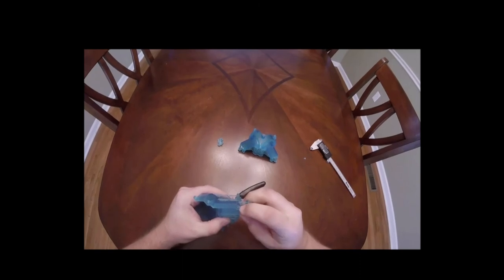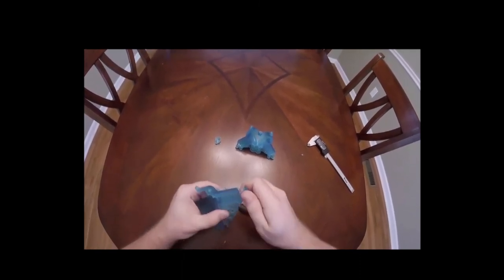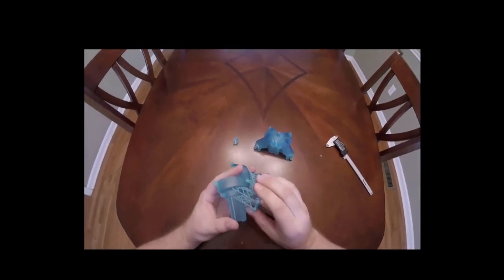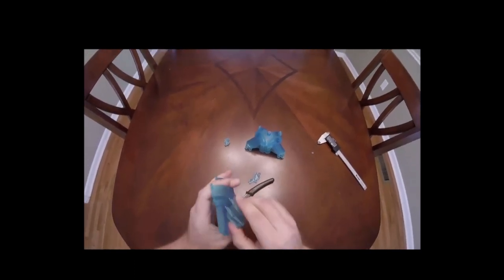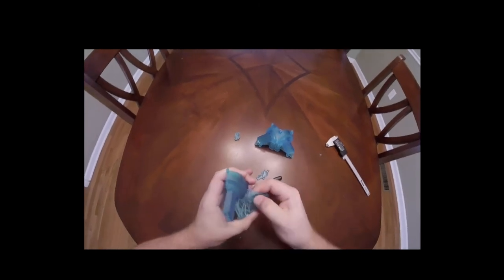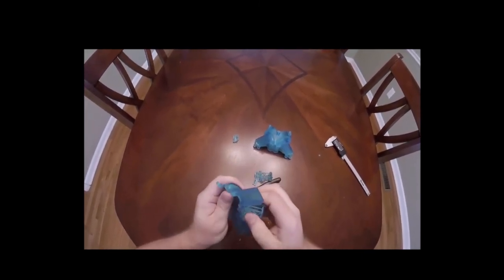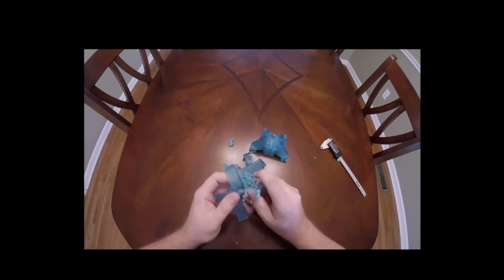And then I'm just going to start looking at how these supports are formed and start fatiguing a couple of these, breaking a couple of these out of the way. And it's all looking really good so far. Remember, I'm trying not to scratch the part with supports, so I'm pulling away from the part as I remove the support structures. And you can see there's very little support artifact left there. I'm just going to keep removing these little sections until I've got this part completely clear of support structures.